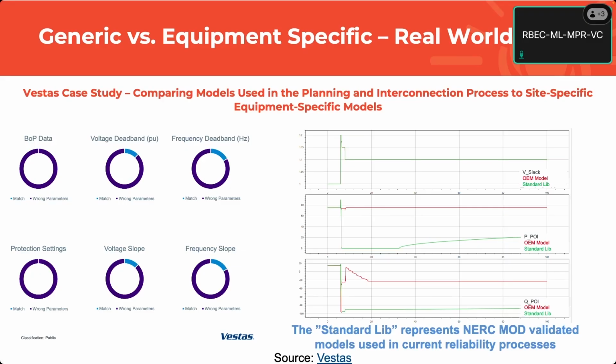Right? How do you represent a continuous curve at the level that we're talking about, and timescales we're talking about, with discrete numbers? But outside of that, there were also just wild misparameterizations, right? And that could be firmware updates that weren't captured in the as-lefts, or a number of reasons, confusions about where protections are, that kind of thing.